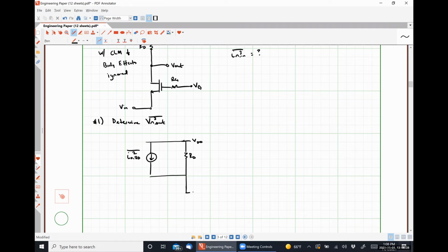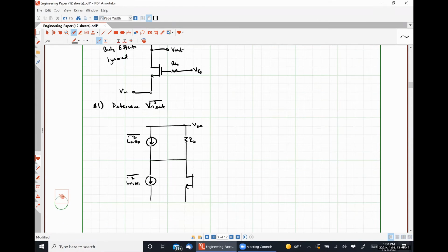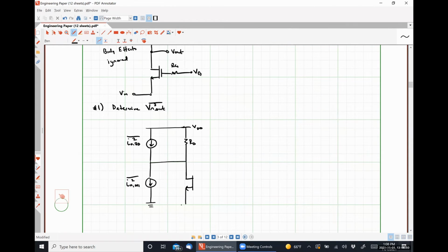We know that our transistor M1 is both a thermal noise and 1/f noise generator. I'm going to call all my transistor noise INM1. That should be connected between the source and the drain. So this is the source. Sorry, that's not remotely the source. Drain, source. And then we have some resistance RG here.